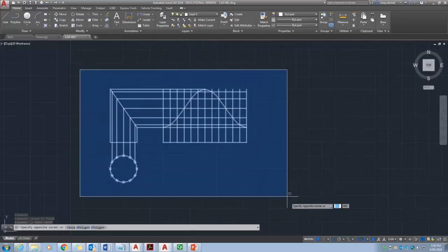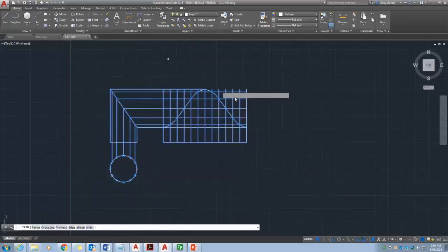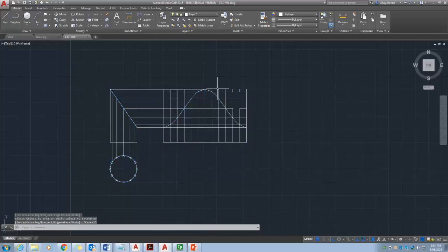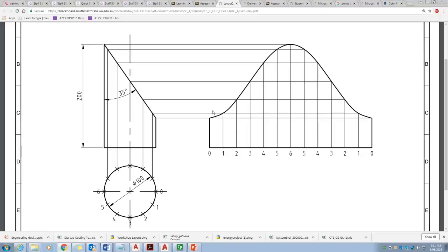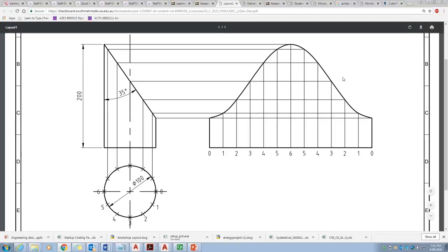It's a delete I was using. So this one, trim, and you can select the trim object. So that way you can trim the objects. So you can trim the portion that you got here by trimming the objects. Okay. So you can eliminate the lines that extend beyond the arc. You really need to stop at the curve intersection here.